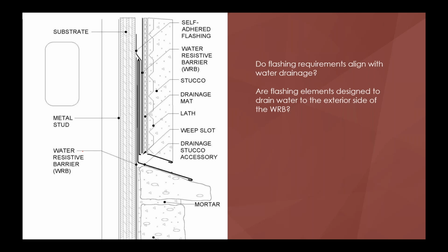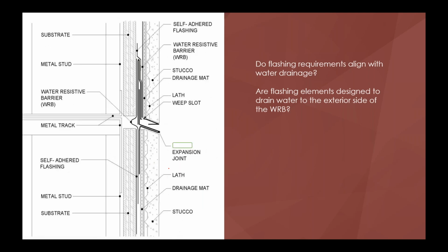And at the weep where any stucco terminates, always make sure that you're wicking that water away from the next cladding. Don't have that water go behind the next cladding. Kick it out. Keep everything separated. And again, this thing is doing the same thing. I got my flashing here, and I got my weep screed here, and I got my exit point right here and right here. I know I'm taking care of all my points there.